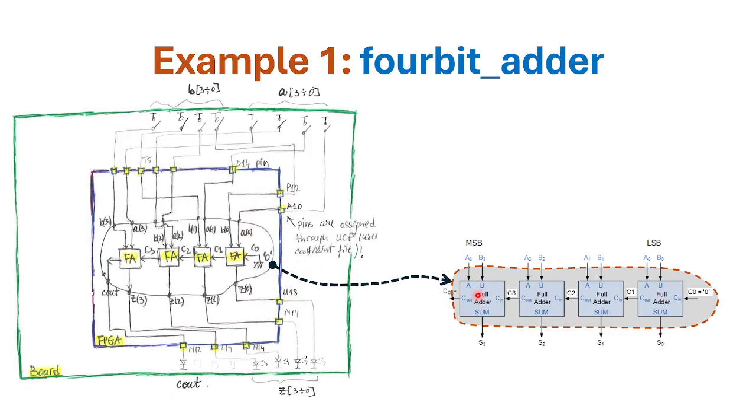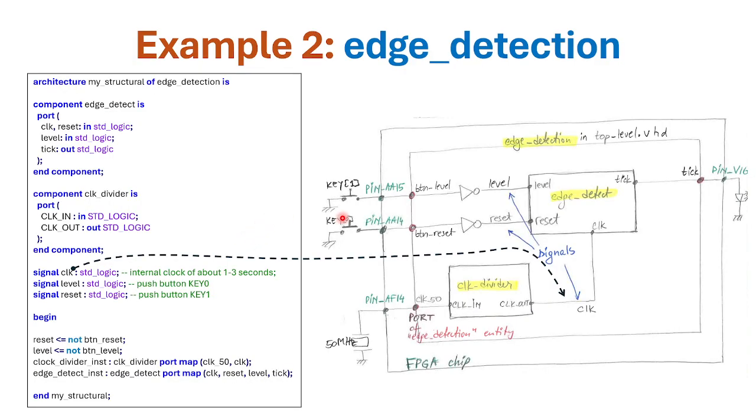All of these connections should be labeled with as much information as available, the names of the pins and the names of the input and output ports and connecting signals.